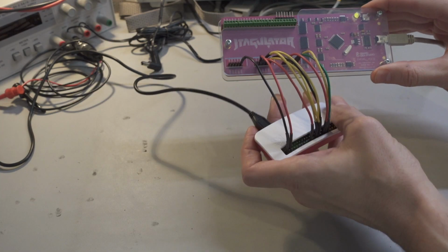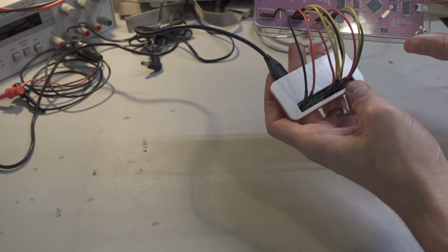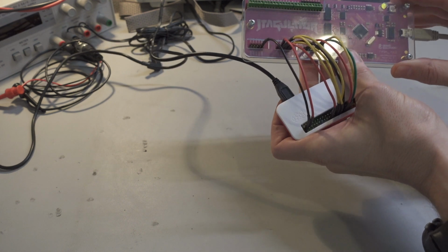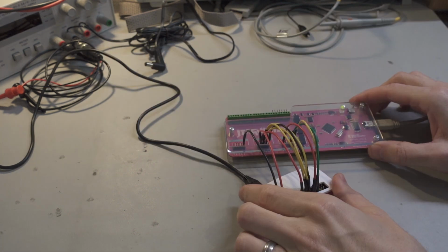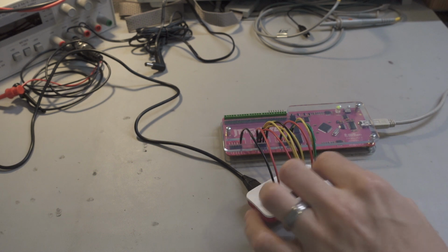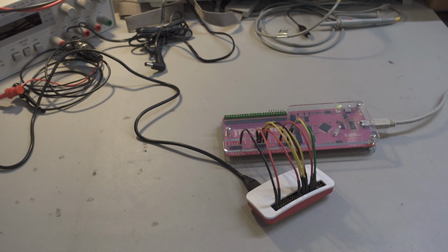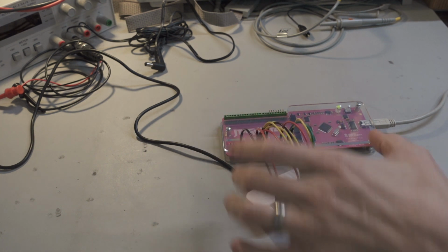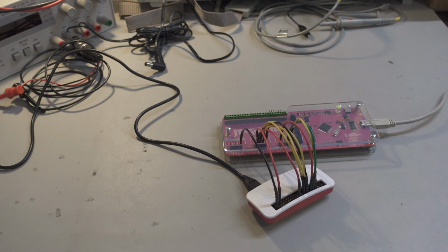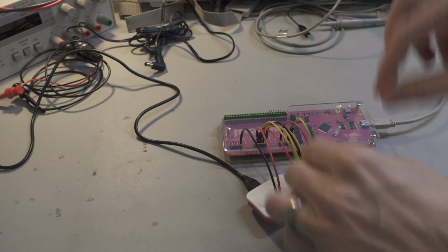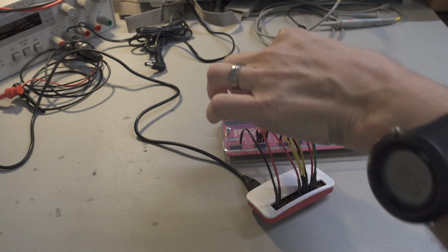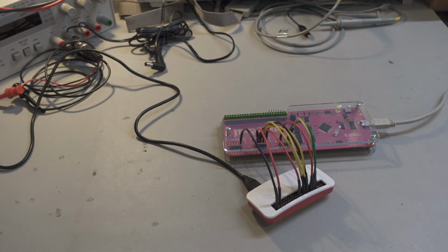For this demonstration, I do have a Raspberry Pi Zero. This is convenient because it has lots of different features that we can show off. With the JTAGulator right now, I do have all of these different pins connected. I don't honestly remember which pins are what, but it doesn't matter because with the JTAGulator, you basically will have your ground connection, which you need anytime you're connecting different pieces of hardware together or different electronic components to serve as that reference. But then you would take your unknown signals from your target and just plug them into whatever channel numbers you want. When we run our scan, it's going to determine what's what for us.